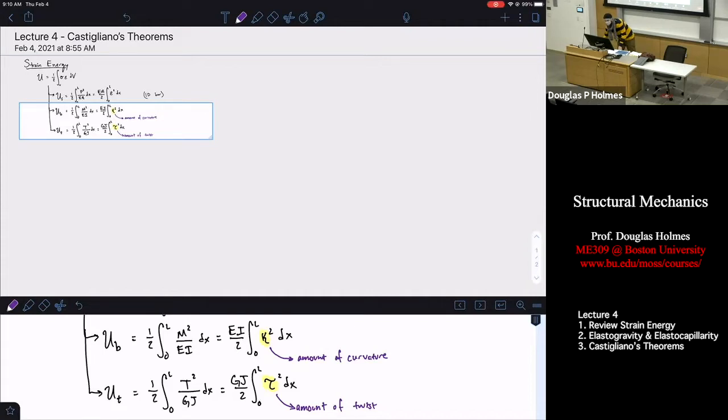What is G and E here? Yeah, good questions. G is your shear modulus, or modulus of rigidity, which is the measure of how hard or easy it is to distort the shape of an object. So, do I have an object in here? Yeah. Here's an object that's a parallelepiped. It's basically a rectangle in 3D. The shear modulus of this object is a measure of how hard it is to distort this from something with a rectangular shape in all directions to a true parallelepiped, like a parallelogram in 3D. You've fundamentally changed the shape from a rectangular cross-section to a parallelogram cross-section. That's what G is measuring.